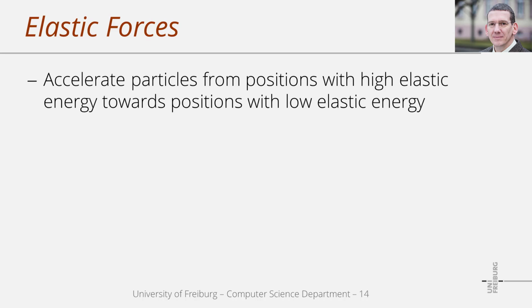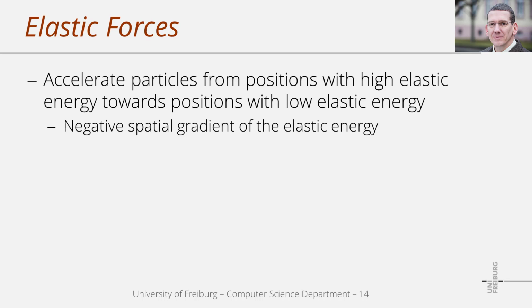So in terms of the forces, we would like to accelerate the particles from positions with high elastic energy towards positions with low elastic energy. And the optimal way to do this is to accelerate the particles in the direction of the negative gradient of the elastic energy. When a particle moves in the direction of the spatial gradient, then we actually get the largest possible increase in the elastic energy.